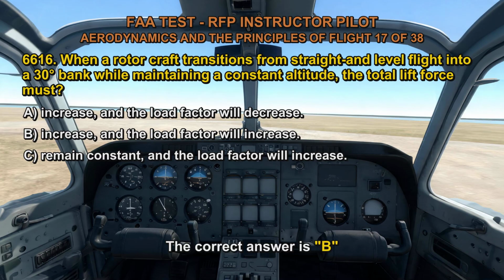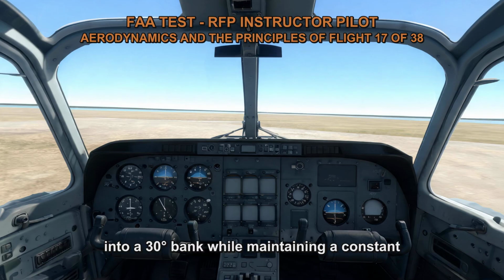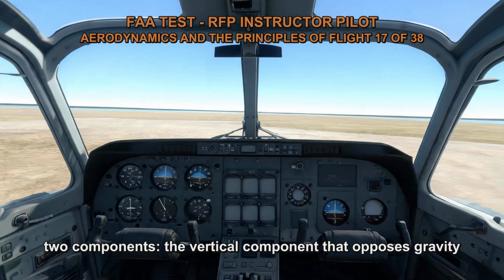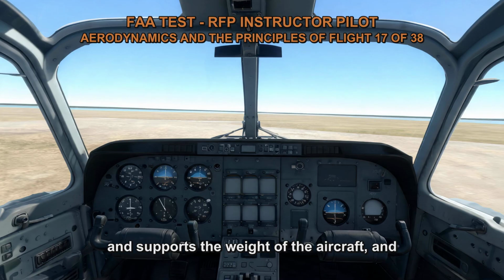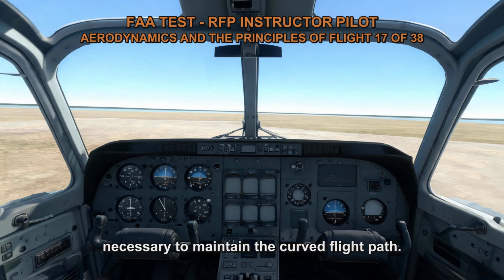The correct answer is B. When a rotorcraft transitions from straight and level flight into a 30 degrees bank while maintaining a constant altitude, the total lift force must increase, and the load factor will increase. In a bank turn, the lift force has two components: the vertical component that opposes gravity and supports the weight of the aircraft, and the horizontal component that provides the centripetal force necessary to maintain the curved flight path.